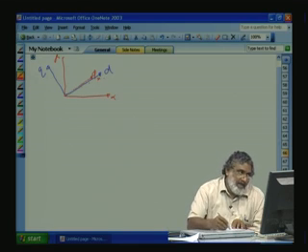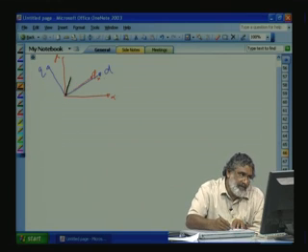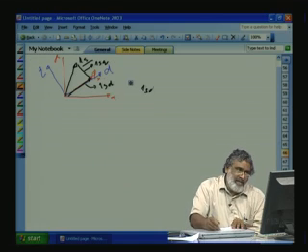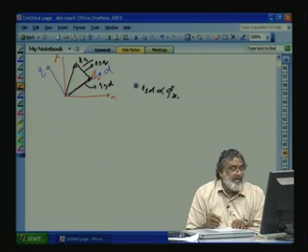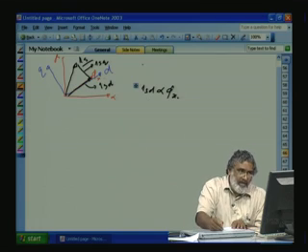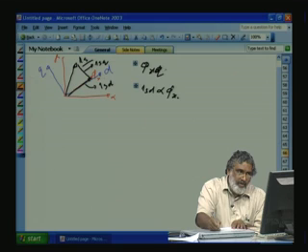Phi r. Now, we have to resolve the current space vector. That current space vector is here. This is our IS, will be splitting along D as well as Q. This is ISD and this is ISQ. So, ISD component will be responsible for the flux phi r. Now, in the new reference frame phi r q is equal to 0. So, let us go to our original torque equation.